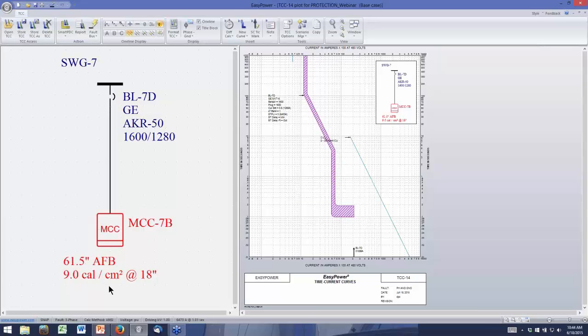So you can see it recalculated. When I lowered it one notch, it went from 97 to 9. And the reason for that is I'm catching the arc flash arcing current in the short time trip. Before it was tripping on the long time, the thermal. Now it's tripping on short time, so it's much faster. So I've sped up the operation.